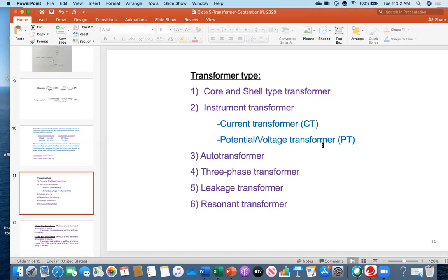Transformer? Don't you use a current transformer? Yes, that is the answer. In the lab that you have done so far, those voltmeters and ammeters could measure only small current and small voltage. Like for voltage, up to, as I said, 208 volt for a three-phase system, or for current a maximum of 30 ampere or 15 ampere. You have not seen more than that even in electrical circuit or electronic experiments.